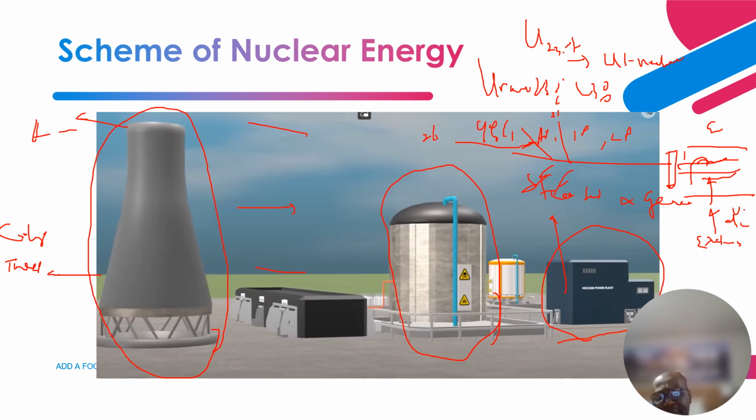Basically, the generator starts picking up speed, and it starts building that voltage, right? So until it reaches the threshold, nominal speed of, let's say, 1800 RPM or 3600 RPM, depending on the number of poles. This is for cylindrical rotors of the steam turbines. Those are mainly 2-pole or 4-pole. Yeah, so that's why they have a high speed, right?